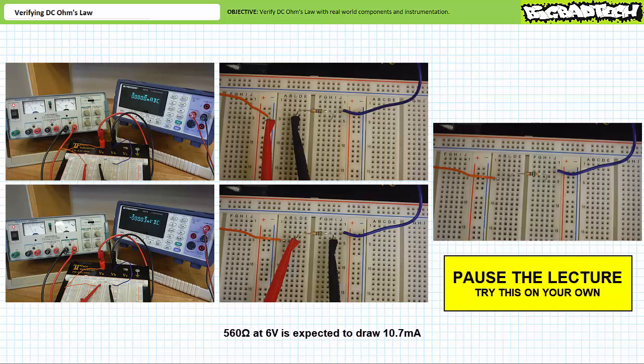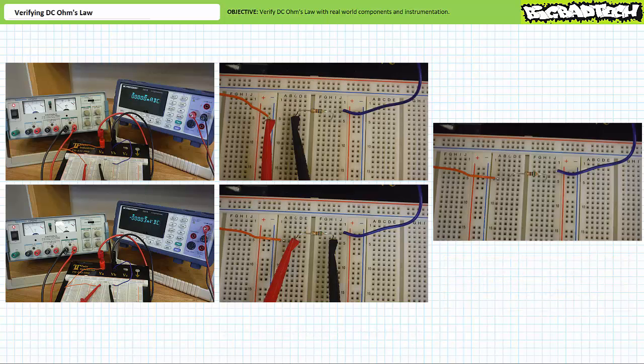If you're tracking, you should have come to the following conclusion. One of the first questions you should ask yourself when you observe no current and no voltage drop is whether you've turned the power supply on or not. You'll be surprised how often this problem is fixed by pushing the button labeled on. In this scenario, however, the source is clearly on. However, we're still not observing any current.